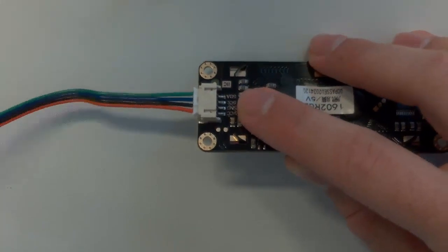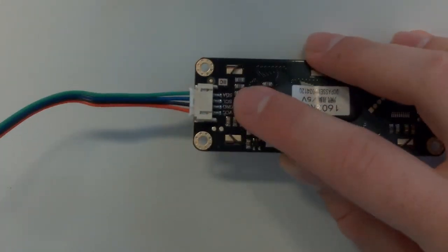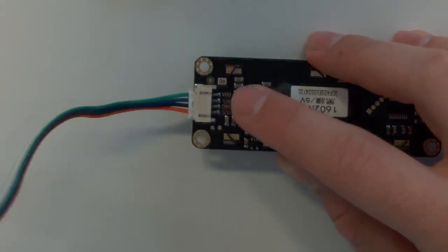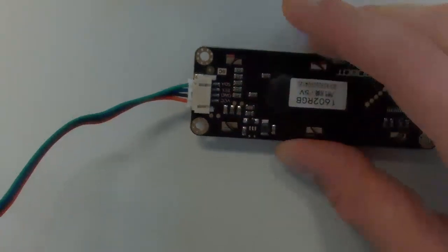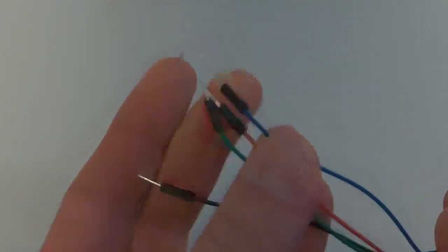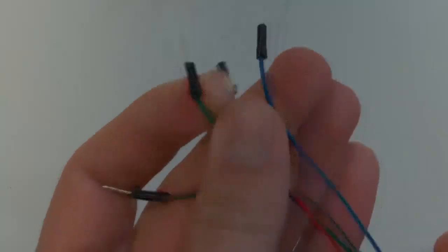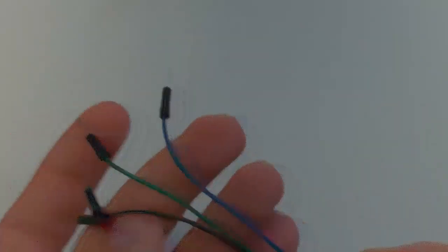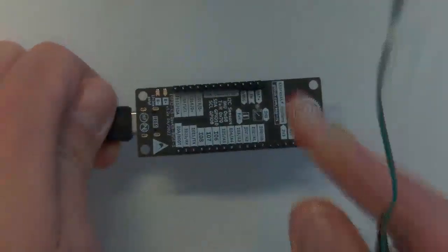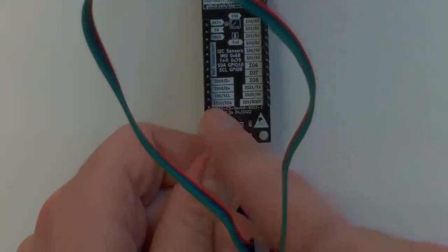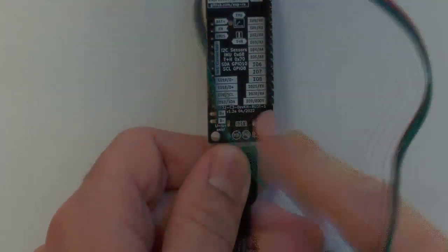So what interface is this? It's I2C. Yep, exactly like you did in lab 2. And now you just have to use this wire. And notice that you will have to plug these wires into your breadboard and get them all connected up. And then on your microcontroller, you can see that there are dedicated pins for the I2C line. So that is how you connect the LCD.